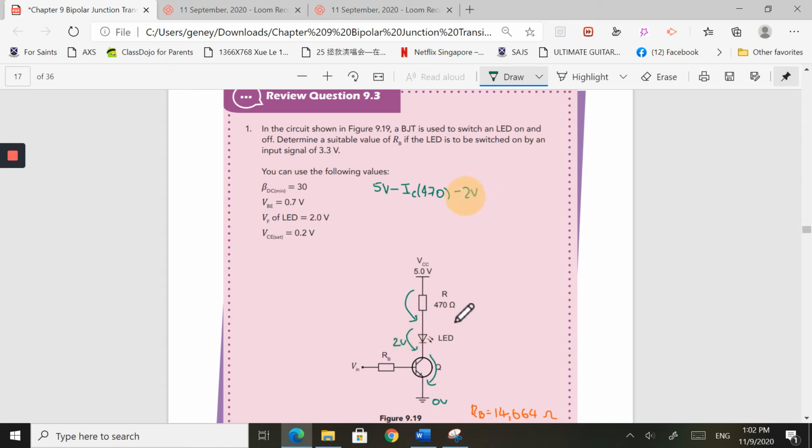I have to drop another voltage here called the VCE at saturation. If you're wondering what in the world is saturation, remember this is the point where the full current flows down. Basically, all it means is that I have the maximum amount of current flowing through here. So I want that value of VCE here because it's the ideal. We want the full value of current flowing through here at saturation.